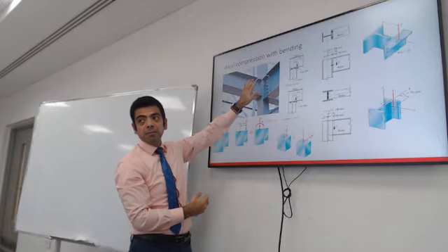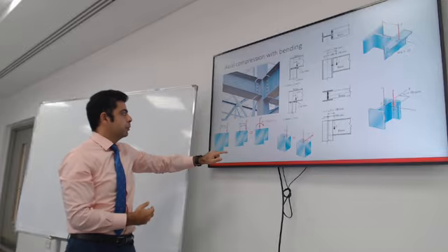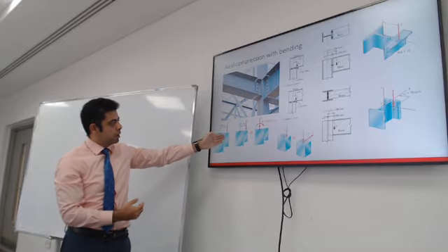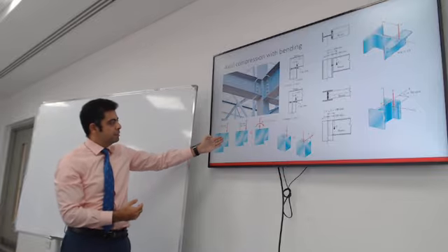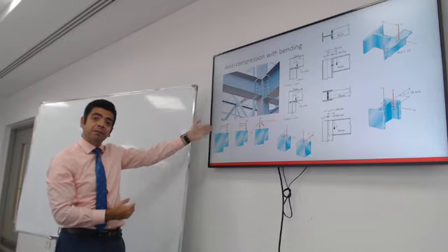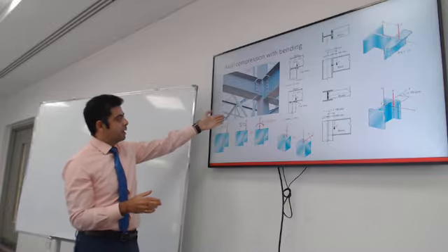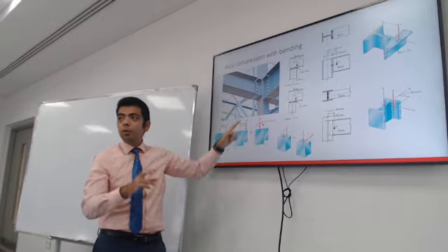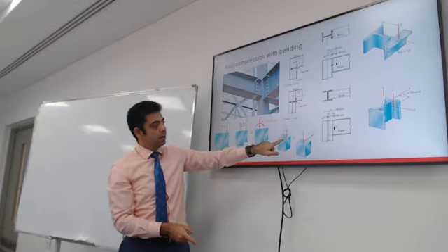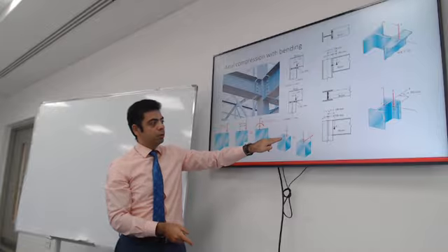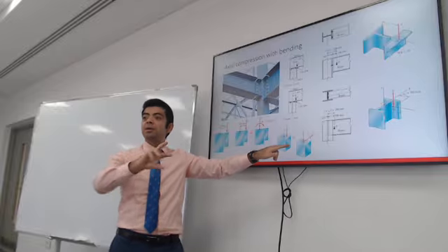The weight of the beam is transferred through the connection at the bolts. So if you look closely here, the bolts and the connection are usually offset from the face of the column, and the face of the column already has a distance from the center line of the column. So this eccentricity, this distance, multiplied by just the vertical reaction of the beam will create an additional moment on the column. So if this column has axial load and the axial load is not applied at the center, this column is going to be experiencing axial load and moment.